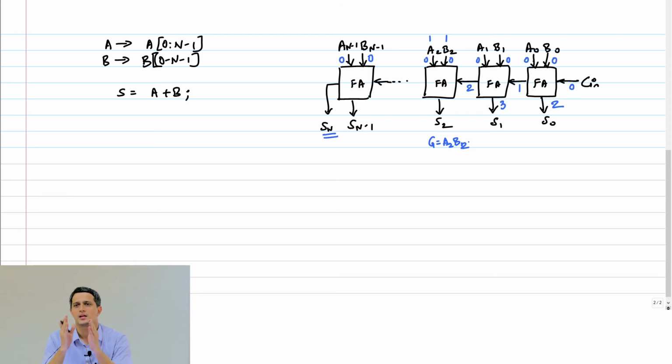So this is the reason we are trying to create these intermediate signals, just to make a decision on whether you need to wait for the carry or not. Here we are not making a decision, we are just evaluating it. Later you will see that I can make a decision based on this information.